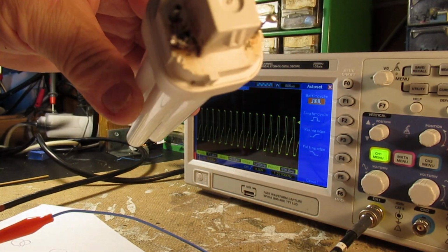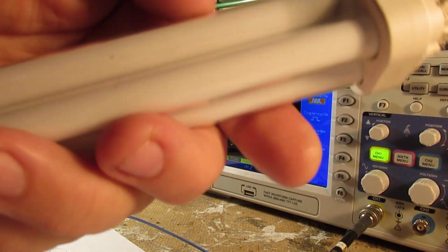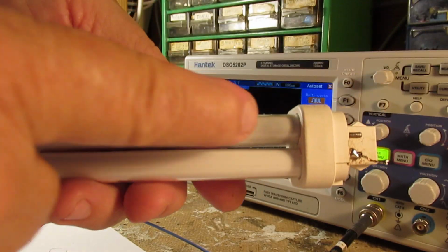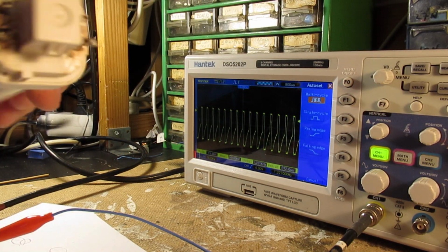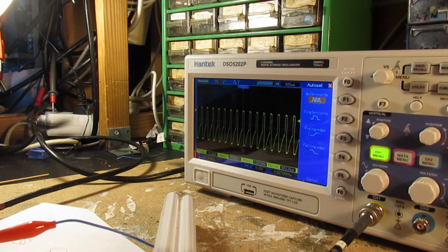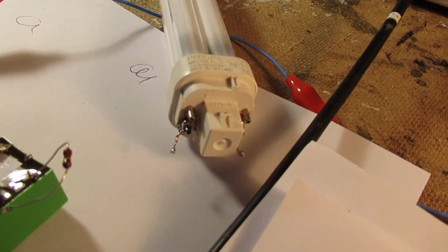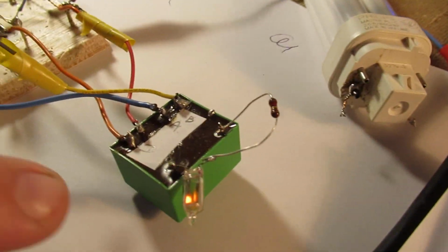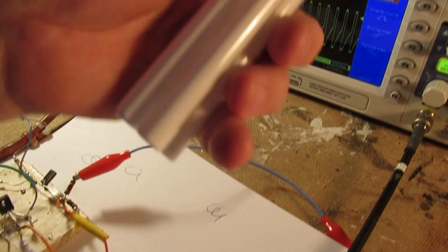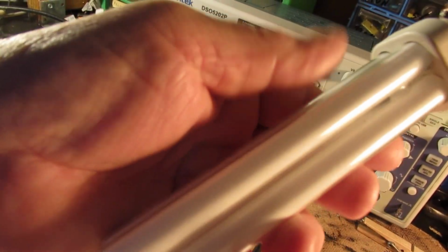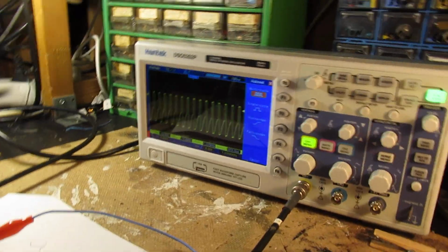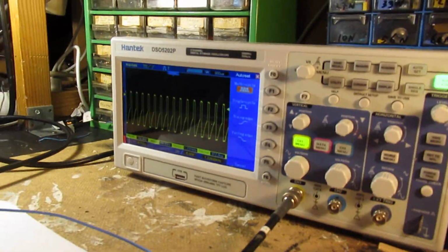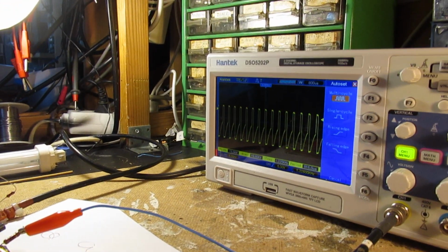All electronics are removed, only the TL tube here is used, and when you connect it to such a transformer, this one to that one, it could be that the tube lights up, and in such a case you know that you have a good high voltage on AC.